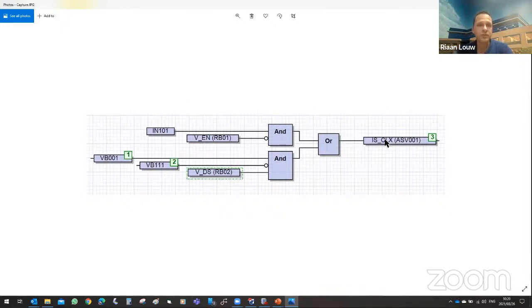So obviously it's important during commissioning and FAT that the hardwire signals are proven. Typically during a FAT, these hardwired inputs will be tested one by one. So the argument would stand that they would be existing and be tested. So when you want to implement a virtual logic in the background or in parallel, this can also then be tested using your functions. So this would be then the output going to the relay. In my case, this is ASV001. And this is now the part that I'm going to move to my relay quickly and just quickly show you guys what my relay configuration looks like.